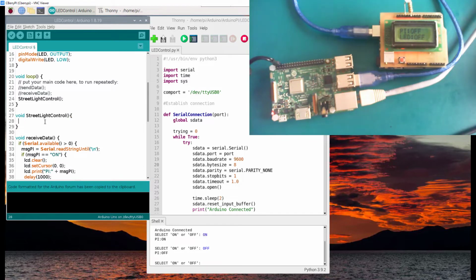The first code we're going to write here is to do some kind of checking. We're going to do a timing comparison here so that we can take a sample, basically a light measurement. I'm going to create another variable of type unsigned long also, and I'm going to call it millis now. Millis now will be millis right at this particular point.